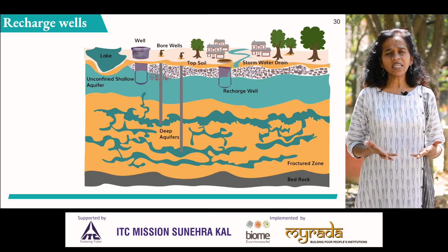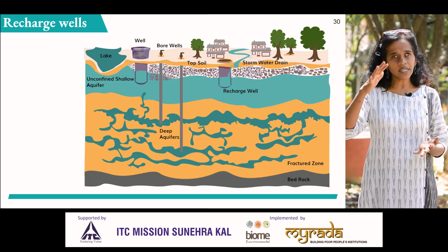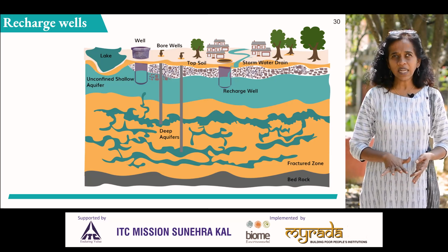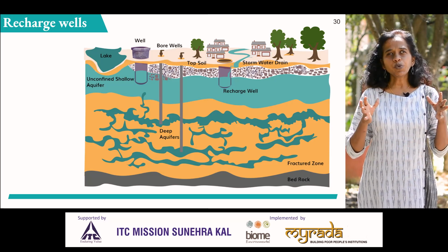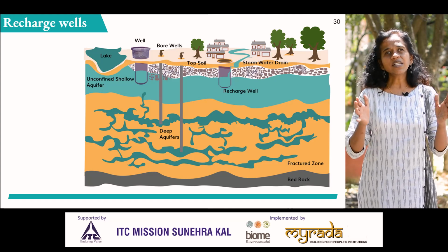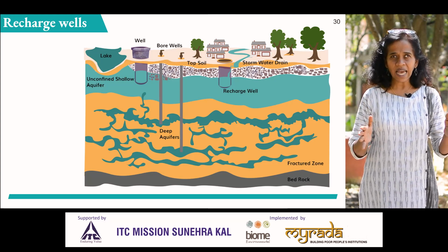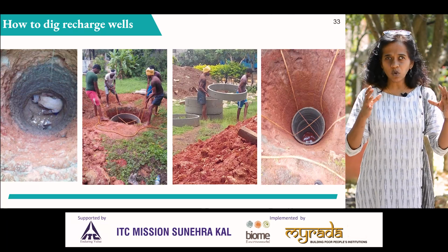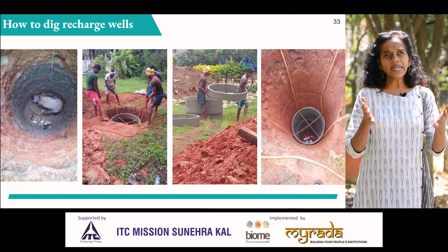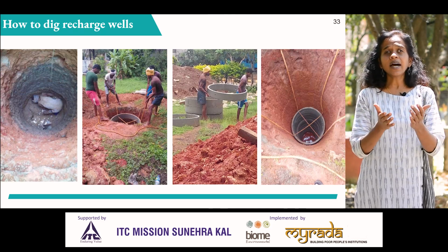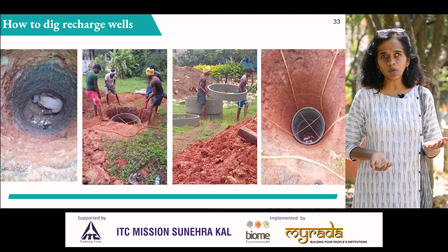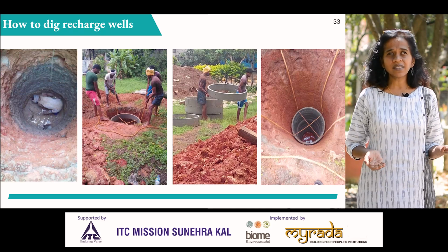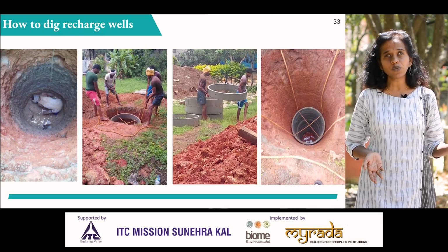Now, when we say recharge, we are really trying to put water into the shallow aquifer as well as the deep aquifer. To put it into the shallow aquifer, recharge wells are our best allies. What is a recharge well? It's a hole into the ground that goes into the weathered zone, 20 to 30 feet deep, dug by the well digging community called bovies. It also provides an opportunity for livelihoods for them.